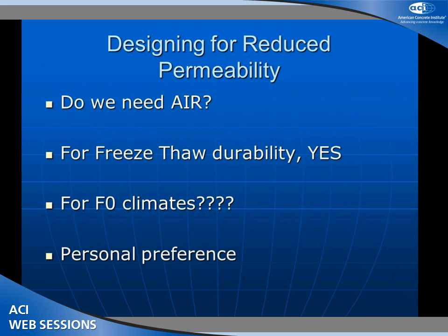It's going to take a high-range water reducer to get the water-cement ratio down that low, even with 50% replacement slag. And do we need air? Well, if we're going to have an FO, like we do in our market down in New Orleans, then we're not going to put air in concrete intentionally. It's only going to be if the specification requires it or some other benefit. Obviously, if we design it for freeze-thaw, we will, but down there we won't.